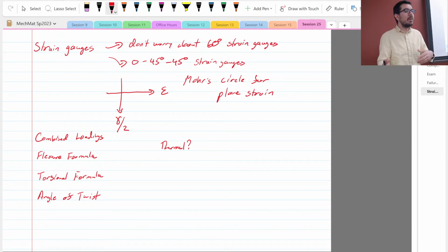When you hear megapascals, a whole bunch of other things come to mind now. Like what are we thinking about with megapascals? What are some of the quantities? Yeah, so it's definitely stress. That's true. We're also thinking about yield strengths. By now you should see the real materials, the ductile ones that we're dealing with, and the brittle ones, on the order of 100 megapascals for yield strengths.